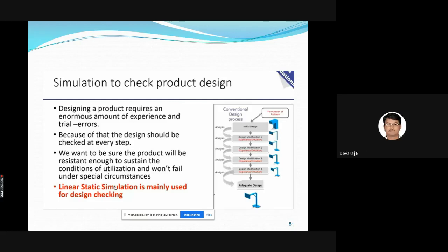Once the design is okay, then we will go for the fatigue or creep or dynamic or mode shapes. Everything will go later, and thermal analysis regarding the application. But first we will do this linear static analysis. Once the design is okay with regard to the boundary conditions, then we will go for fatigue, creep, dynamic analysis, then thermal analysis. Whatever you want, you can do later.